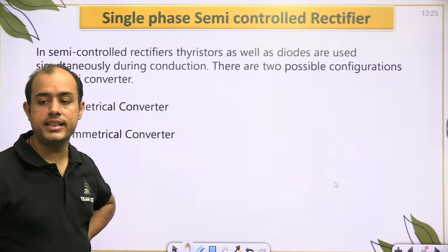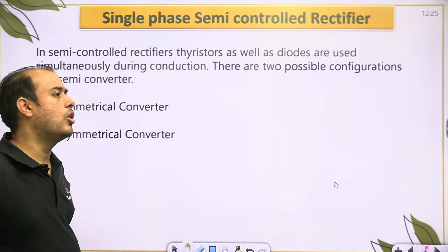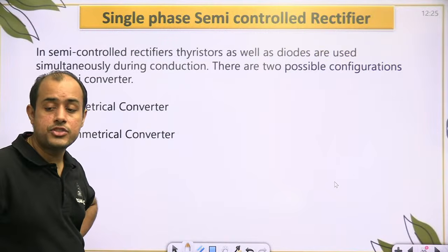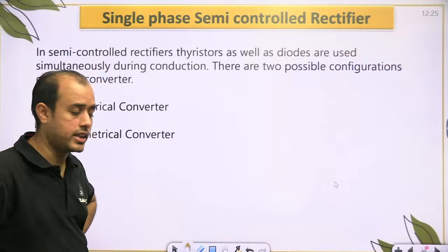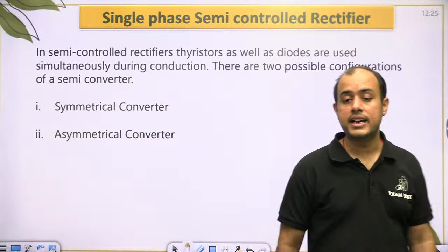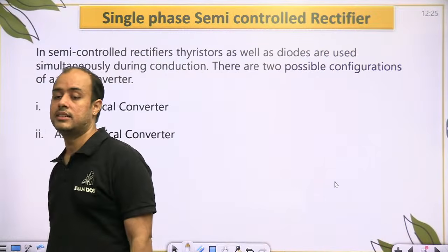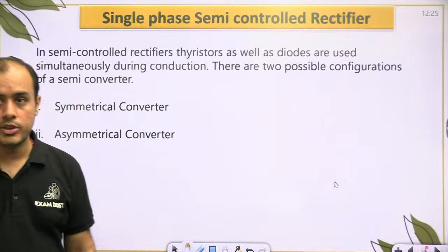Does current increase here if beta is greater than pi plus alpha? Actually, Sandeep bhai, always remember, average value is higher in a discontinuous conduction rather than continuous. So if beta is greater than pi plus alpha, average will actually be smaller. Average will be lower in continuous.